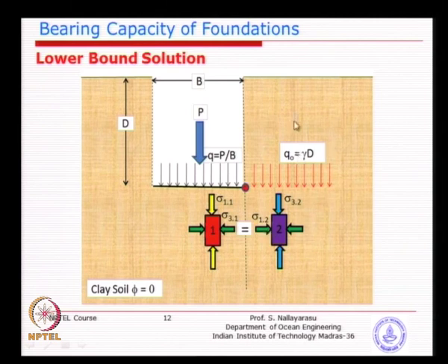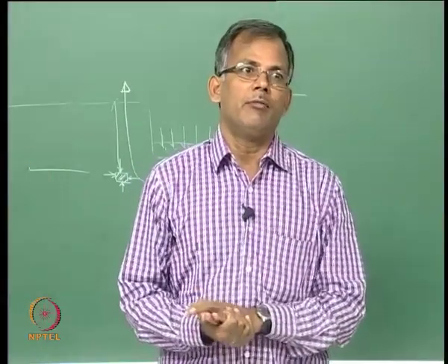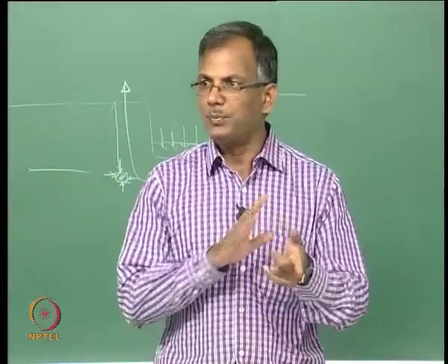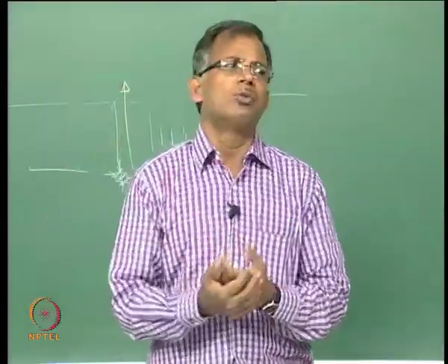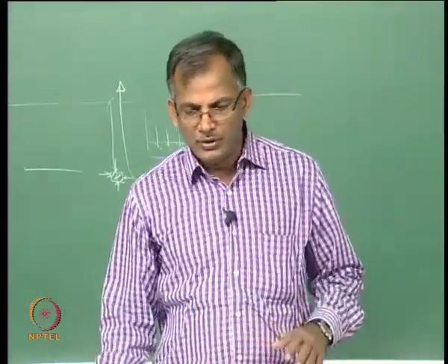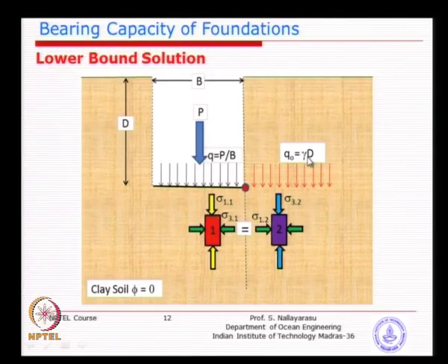Imagine if that is not the case, we can always go and put some weight there, isn't it? The larger the weight you put on the sides, the more pressure you can apply to the foundation itself. So, that is the idea. You can see here the very important matter is the active and passive earth pressure cases, and the overburden pressure, the weight of the soil on the side, is going to be very important. As long as you understand this principle, this is the principle that will be adopted almost throughout foundation design. That means the evaluation of overburden pressure is an important activity in the whole process of estimation of foundation capacity.